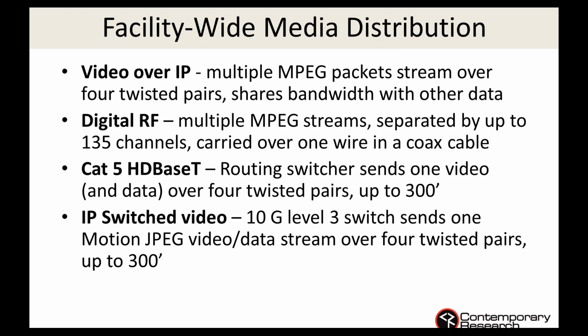So motion JPEG is a technology that's free. So it's easy to incorporate in your system, and it carries video very well. That's what you see in movie theaters, a special version of that. And there are lossless versions of it that can carry the video with very low latency. There's going to be some, but generally not so much that you can notice. As you compress the signals more, when a lot more channels start happening over there, though, you will see more latency because you have to compress the videos more to get all the videos through the same switch.